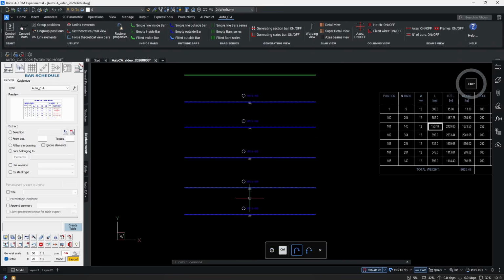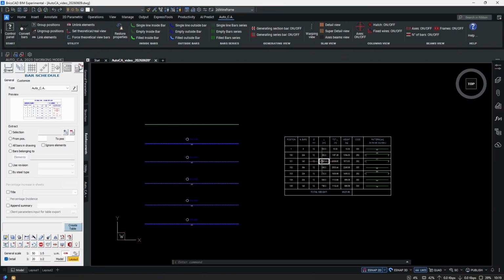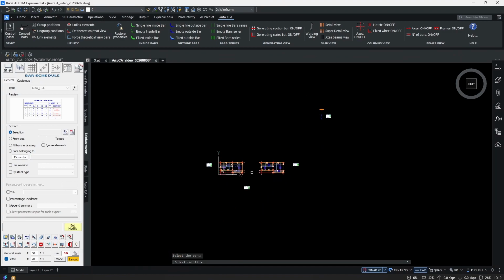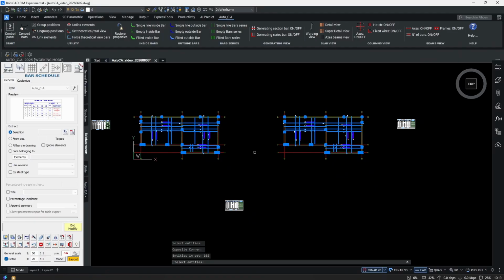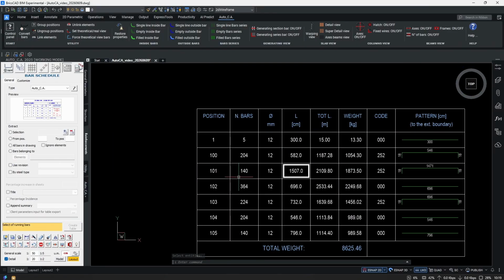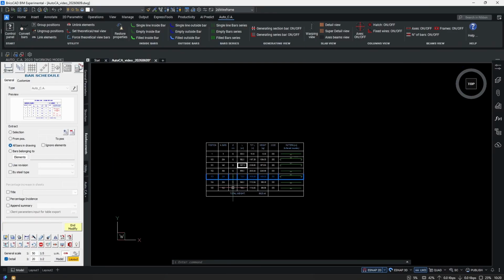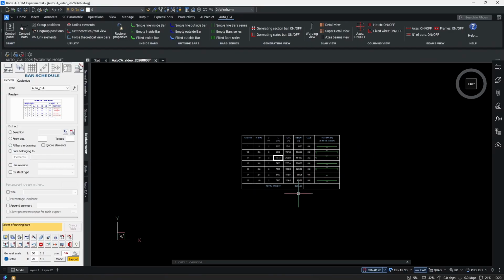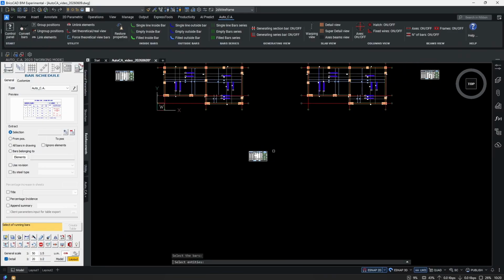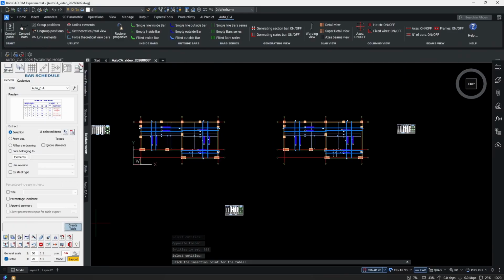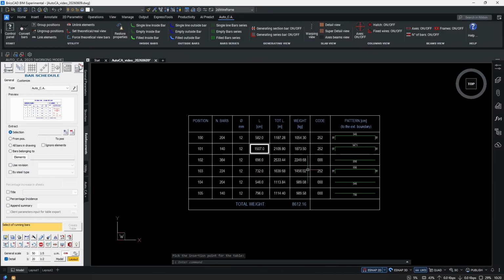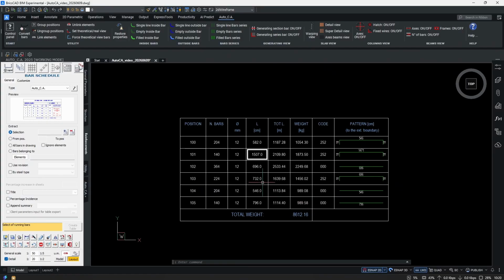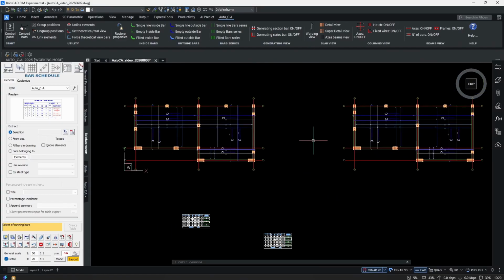As you can see, we selected to group everything together, so we can get back to the selection only and select only those bars we will want to see. It seems that you cannot change subsequently the type of the table, but you can always create another bar list only with the selected elements. So this is all bars in drawing. This is only the slabs we created.